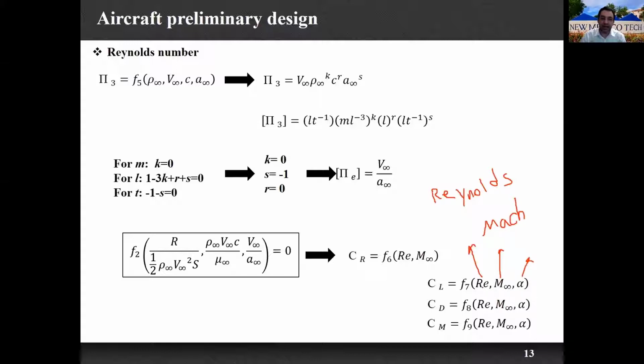So once you have any type of aerial system moving in the air, these are three conditions that determine the regime of the flow. The first one is the Reynolds number that we discussed. We said that the Reynolds number is equal to the density times the free stream velocity of the flow or your object times c, which is the chord length, divided by dynamic viscosity.